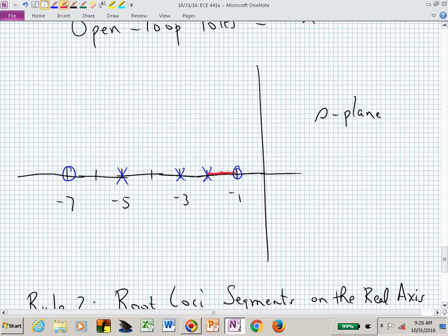Now, putting this back in is going to be a trick. All right, do we see that that contributes -180 degrees? Do I have your attention now? What's the angle contributed by that pole at -2 to any point on that line segment? How far do I have to move my head if I'm looking to my right? If I'm at -2 and I'm looking right, what's my angle? 0.